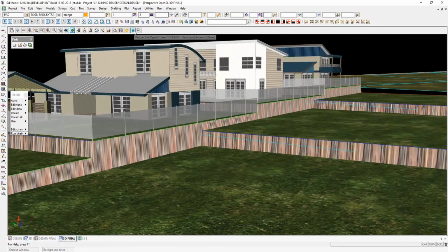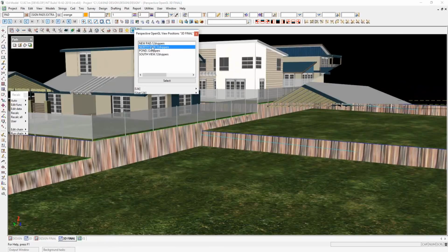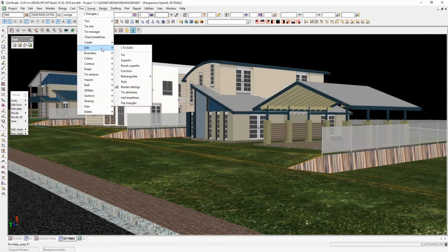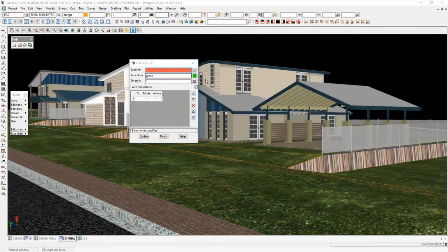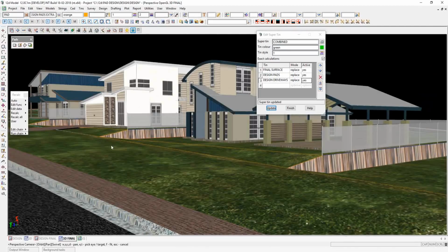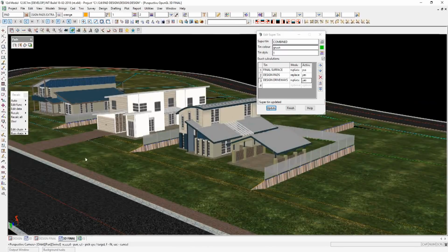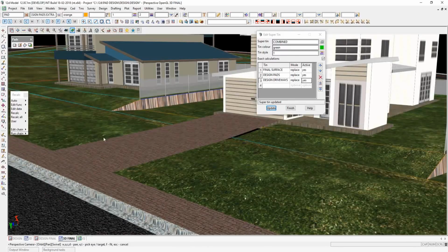So we look back in our north view, and this tin I keep on running in the chain is just a super tin, called combined. So it has the final surface, the pads in there. It also has the driveway. So if I add the driveway in and update, we've now got the driveway over here. That's the one that I showed before where we turned the shade or the texture on and off. So it's also used the pad option to grade the actual driveway.